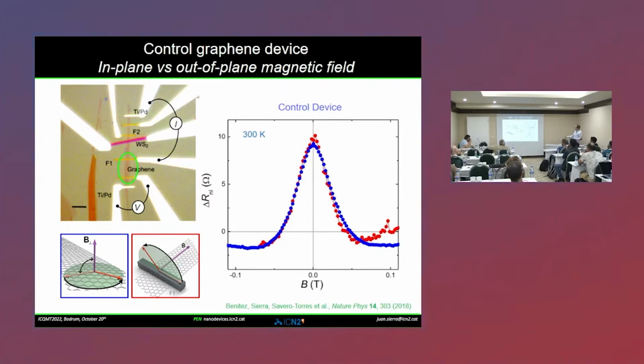So you see that here we are in the band gap of the TMD, and then it starts to conduct electricity for this gate. So we did this as a function of the electrostatic gating in the system. With this electrostatic gating, I didn't mention before, we are able to control the carrier density in the system. Okay? So by playing with this, we can know when this TMD starts to conduct.